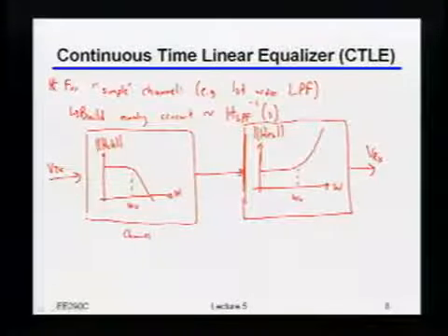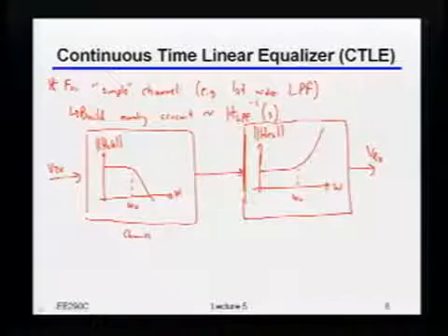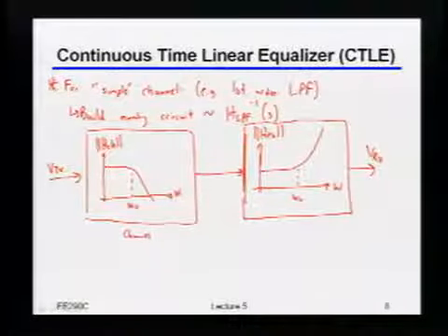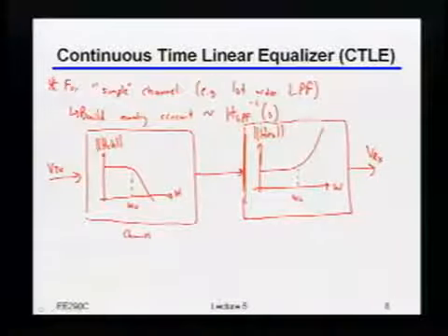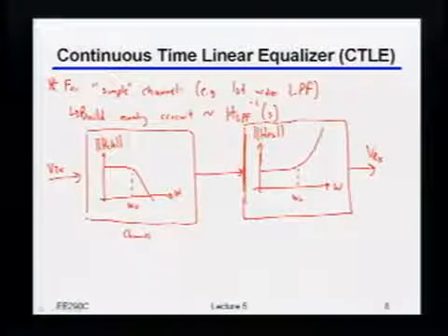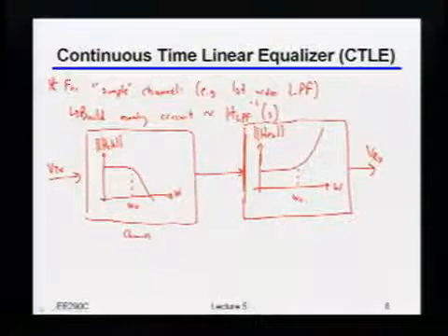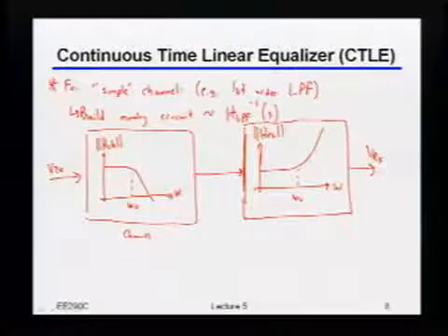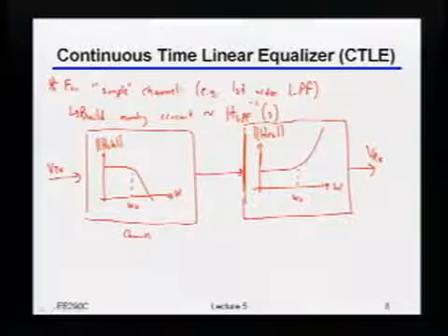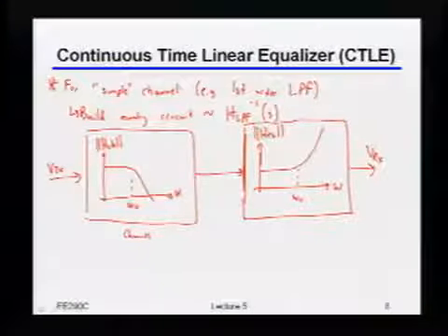Okay, so I'll remind you guys how we actually build this in a second, but any thoughts on whether what I wrote here, even for this very simple example, works exactly the way I said it does, or are there maybe some issues we have to worry about? Yeah? There's phase distortion. Okay, well that's fair. But my intent was really to take H inverse in the S domain. So whatever the S transfer function was for the first one, I'm literally going to try and do the inverse of that for the second one. So that would take care of the phase distortion too.